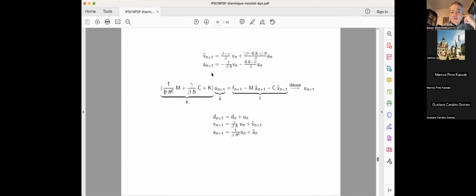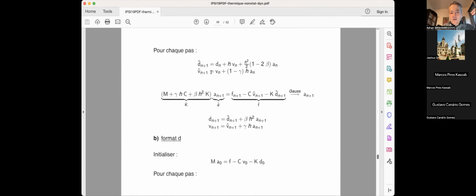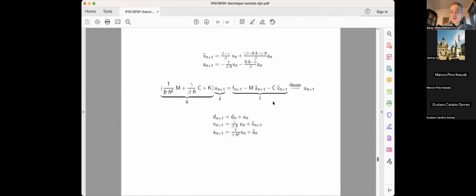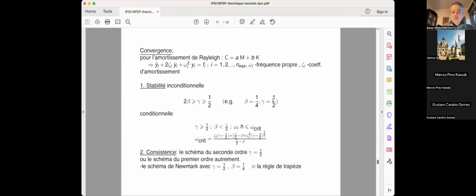So basically, the idea, either A format or B format, you cancel the whole set of the unknowns, and the main cost becomes the solution of the set of algebraic linear equations when you discretize this, either computing d_{n+1} or incremental displacement, and this will be the dominating cost. So the game after that is to say, can we judge the stability, consistency, and so on and so forth? You can rely fully on the analysis done in the heat transfer case, and I'm going to go into detail that basically what we do, we kind of diagnose the system.